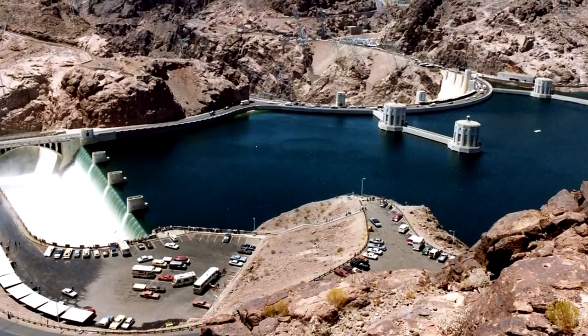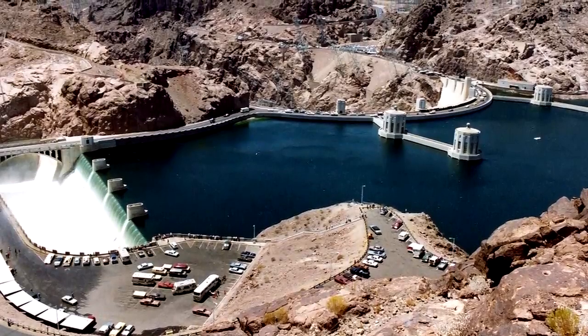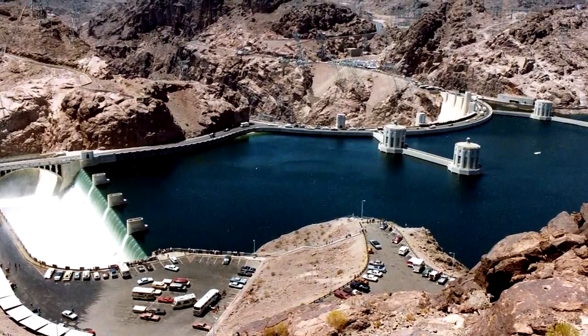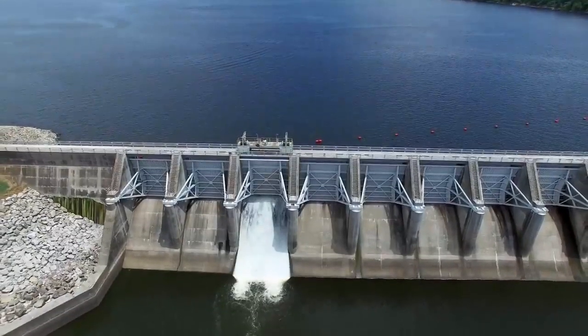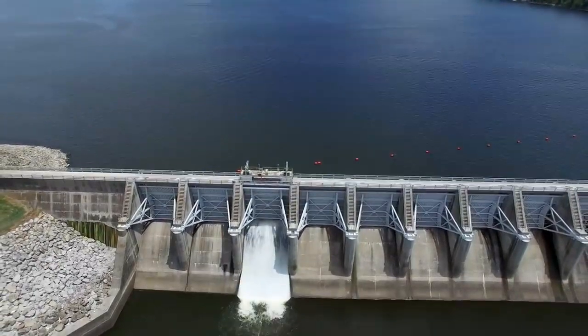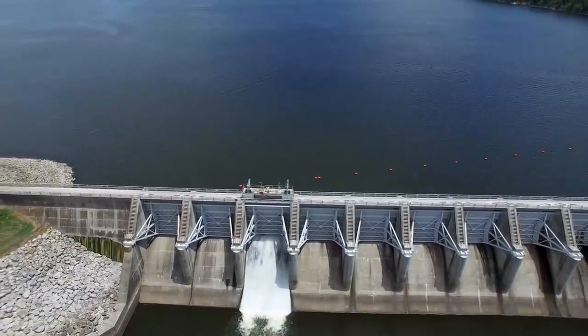Of course, this challenge is easy to address if we allow for structures with moving parts. Many dams and spillways have large gates or valves to control flow. There are a wide variety of types of controlled outlets used on hydraulic structures, including crest gates that act like weirs that can be raised or lowered. The benefit is that the structure's capacity can be increased while flows are high by opening gates, and then decreased when flows return back to normal.